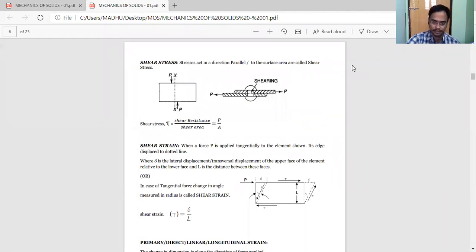So this is shear strain, this del divided by this length L. You won't find a change in dimension here; this dimension will not change, but it changed its position. The dimension that is changing is this one. So say this is L. The change in dimension L is considered to be this del. So this del by L is the shear strain.